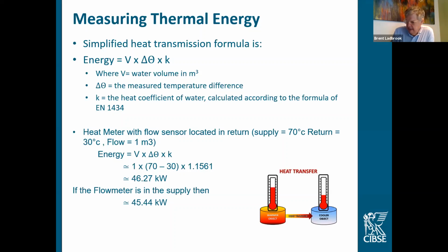So imagine a QP 150 measuring 150 cubic meters per hour for many, many years. This adds up to a heck of a lot of potential errors if we don't set up our meter correctly, and we must tell our thermal energy meter where the flow sensor is.